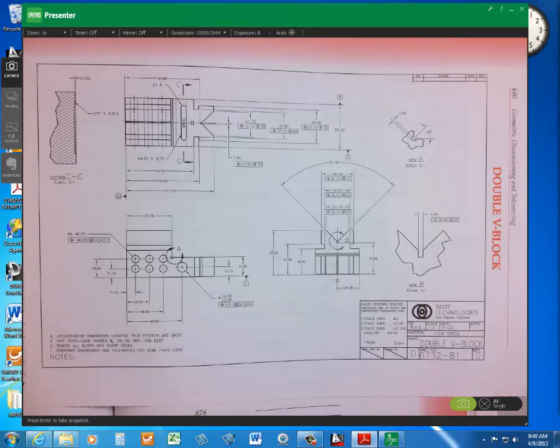Normally, we keep the zero on the front end if it's what, inch or metric? Metric. So it's just the opposite. And then we chop the zero off. We don't have a placeholder zero as a rule. It's not supposed to follow it if it's metric.